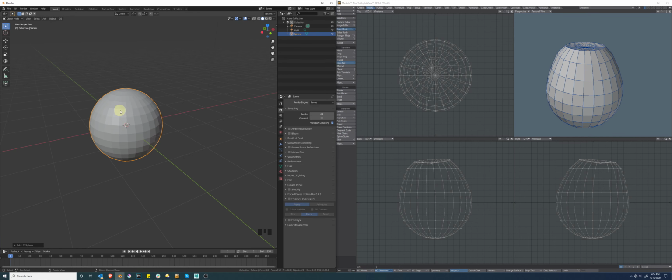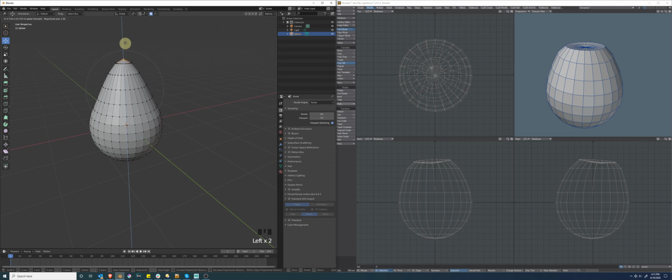Okay, we can do the exact same thing inside of Blender. If I jump over to Blender and I click on my object and I jump into edit mode, click to deselect, and now I select that top vertice. I go into the move tool and I click up on the z-axis. This begins to behave exactly like Lightwave, Modo, Maya, 3D Studio Max, etc. If I want that falloff, I have to come up here to the top, and this circle with a dot in it is called proportional editing. If I click and turn that on and then drag again, you're going to see that I get the exact same effect as I was getting from Maya and from Lightwave.